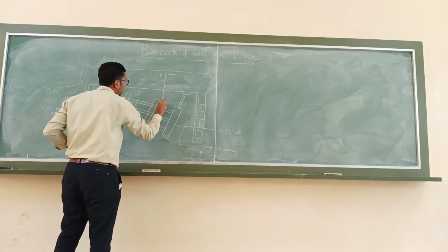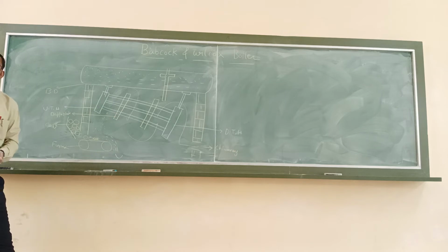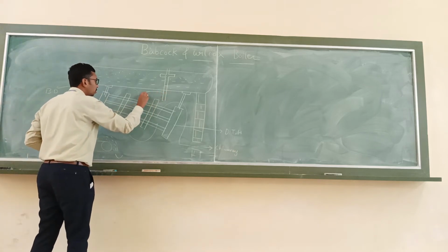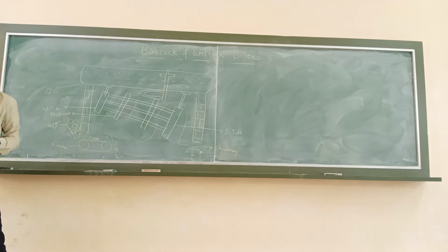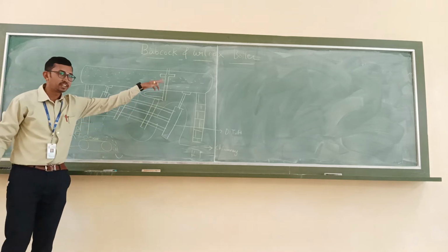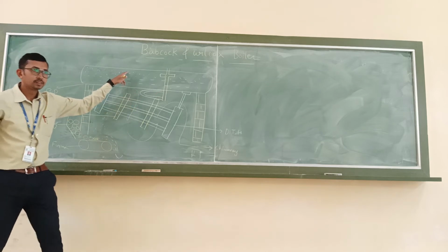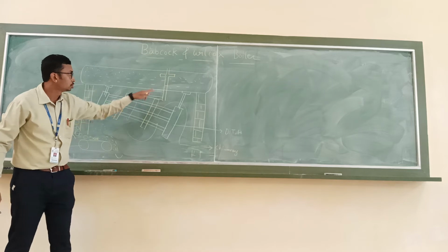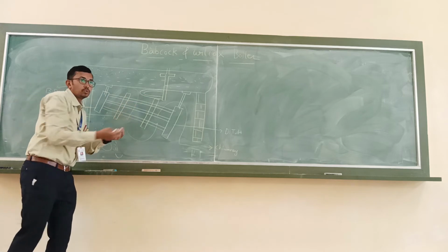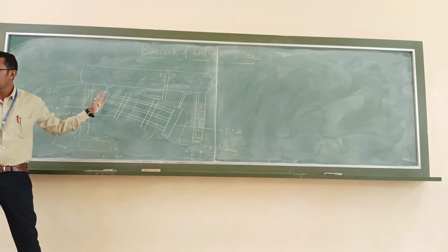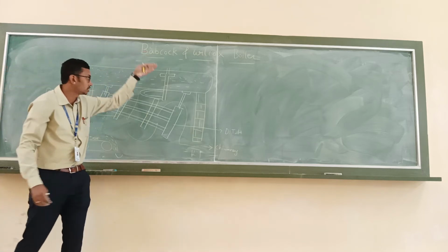T tube. What is this? T tube. And this T tube is connected with U tube. So the wet steam will go to U tube through T tube. Where once again the heat will be extracted from the hot gases and it is going to produce the superheated steam. So this is a cross sectional view, right?